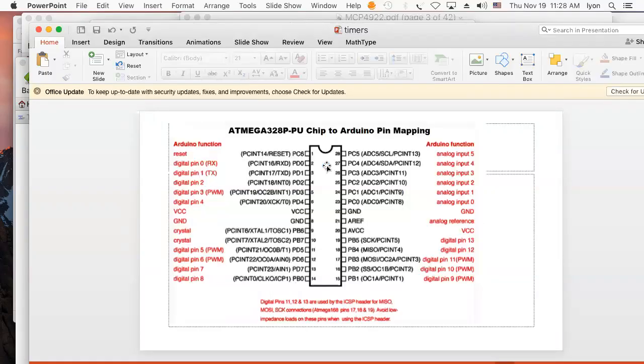And one of the things you can see when you go to these different pin numbers is they somehow map to pins on the actual 328 CPU. I think we said it was going to be pin 8. There's digital pin 8, and that's on port B. And then somebody said digital pin 9.